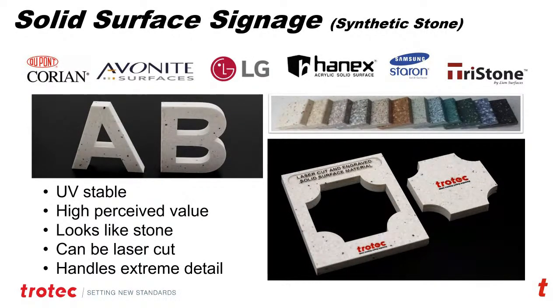And I'm going to show you a couple different examples here. Cutting it, you can see the raised letter signs look like they're actually molded that way, but they come right out of the laser system. A little bit of dust on the edge. And this is the Avonite brand that I'm using right now. But DuPont's Corian, LG, there's a lot of different ones out there. Make sure you test it before so you understand how the laser is going to perform. Sometimes they put additives into certain colors or it doesn't perform the same as in this case that you see here.